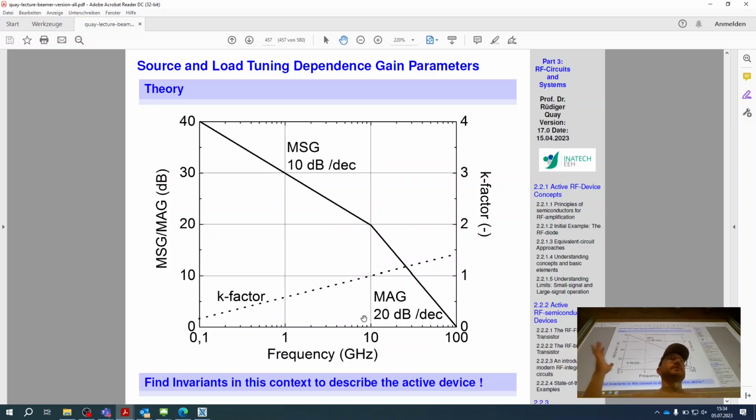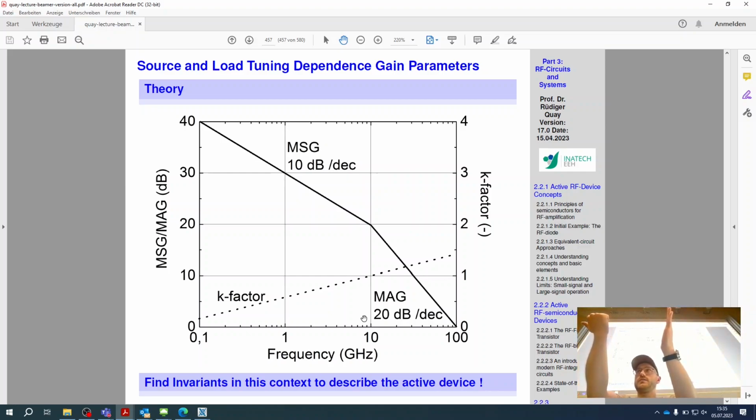It starts to oscillate because at some frequency point you get a feedback loop due to having a wrong impedance target. Your complete wave gets reflected back at the output. So you have a block, a two-port device. You try to push in a certain frequency from inside or from the outside. Usually it's output instability or output oscillation. You try to push in a wave from the outside, and it gets reflected back.